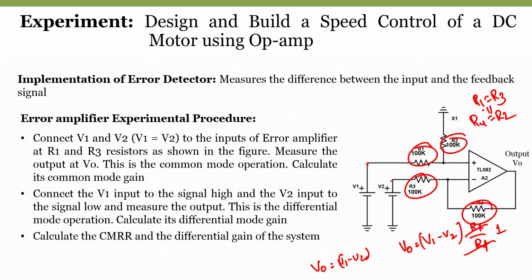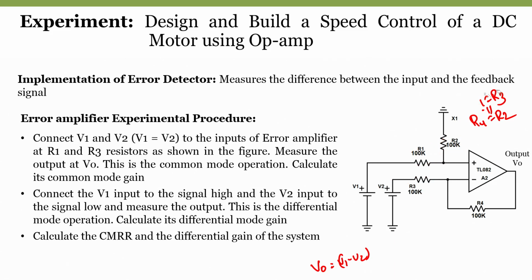That may be the problem with an instrumentation amplifier. Few instrumentation amplifiers have a gain starting from 5. In the commercially available monolithic instrumentation amplifier IC, the minimum gain is 5. Since that is not possible in this case, we have to go with a high input impedance differential amplifier. We already know how it works, so let me quickly look into the simulation.